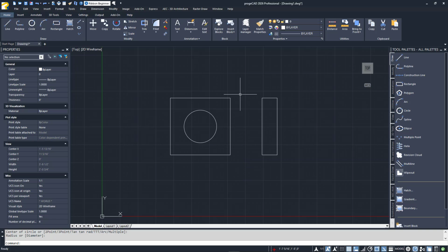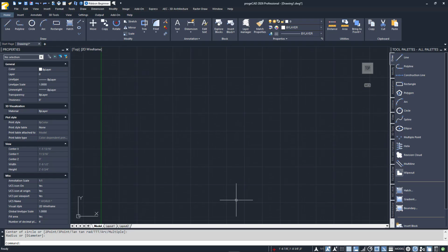The last two drawing precision tools we're going to discuss are Snap and Grid. They are also toggles on the status bar. They are on the far left side and appear as an array of dots and a very small grid of intersecting lines. They too have function key toggles. F9 is for Snap and F7 is for Grid.